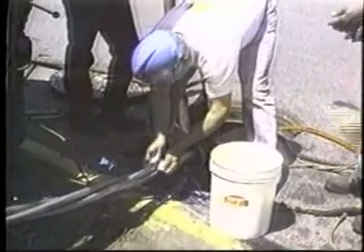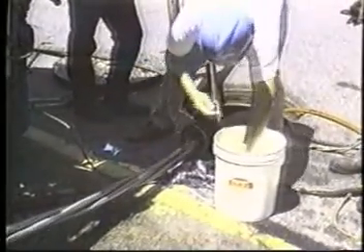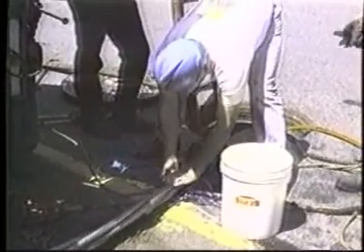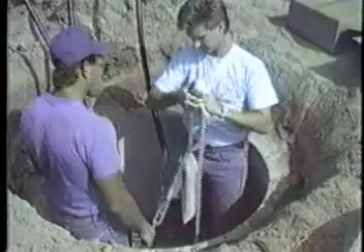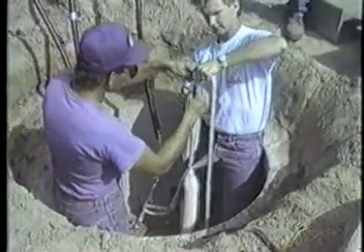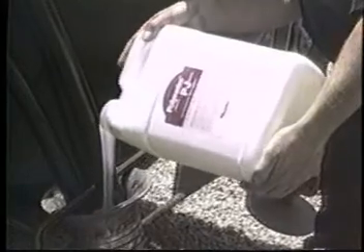Lubrication will be needed on most long pulls. Many ducts are available as pre-lubricated, and specialty lubricants appropriate for pulling fiber optic cable are available from a number of manufacturers. These lubricants are usually water-based materials with soluble high polymers, which make them slippery. Some contain silicon oils or microspheres that act like tiny ball bearings to reduce friction. For long pulls, it is important that the lubricant completely coats the cable jacket and stays on the cable through the length of the run.